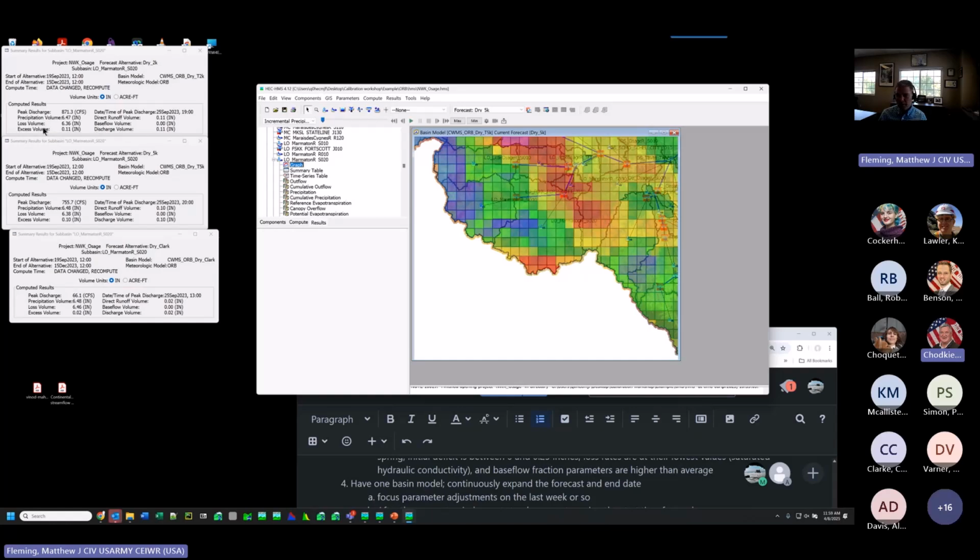That's because with the CLRH method, we're averaging the precipitation intensity across all the grid cells. So if your constant loss rate is 0.1 inches and the area averaged precipitation is 0.09 inches, then you get no runoff. With the Mod-Clark method, we're doing computations on each grid cell. So if the rainfall in this grid cell is 0.2 inches, then we have excess, versus if it was 0.05 in this grid cell, then we have none. So there's a difference spatially with these methods, and you just have to be careful. If, for the events you care about, there's variability in the spatial precipitation, then you can't go with the CLRH method.